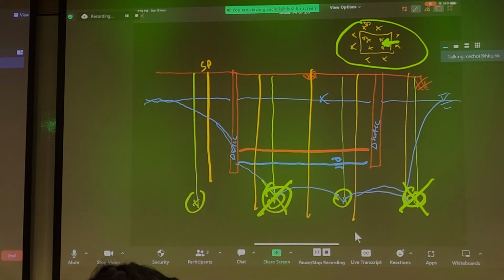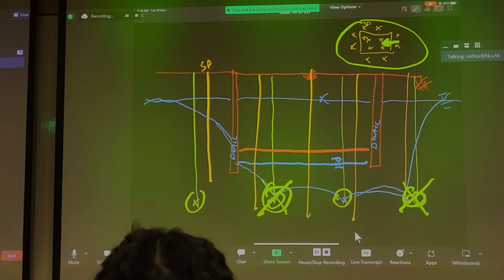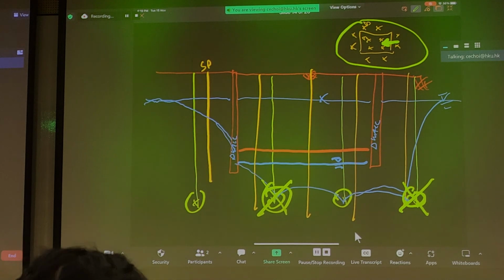The first function is, can we draw down to the expected working level? Number 2, what's the recharge rate? And number 3, I mentioned it earlier, sorry, there are 3. What's the subsidence caused outside? Was there any settlement? So besides purely looking at SP combinations, you probably also have settlement markers outside to detect if you're getting ground subsidence purely from drawdown.